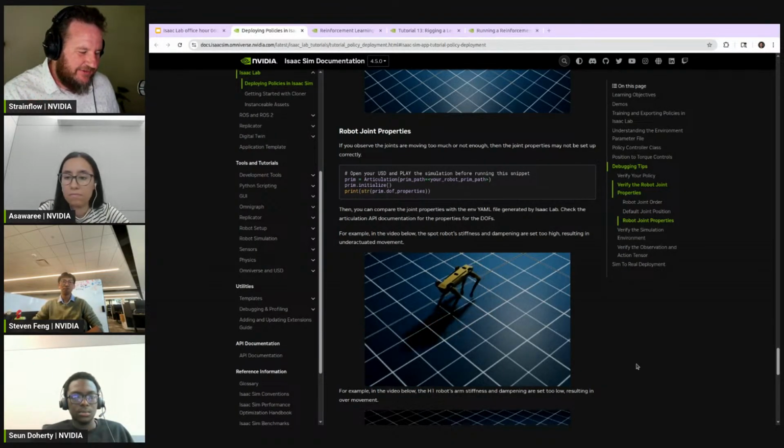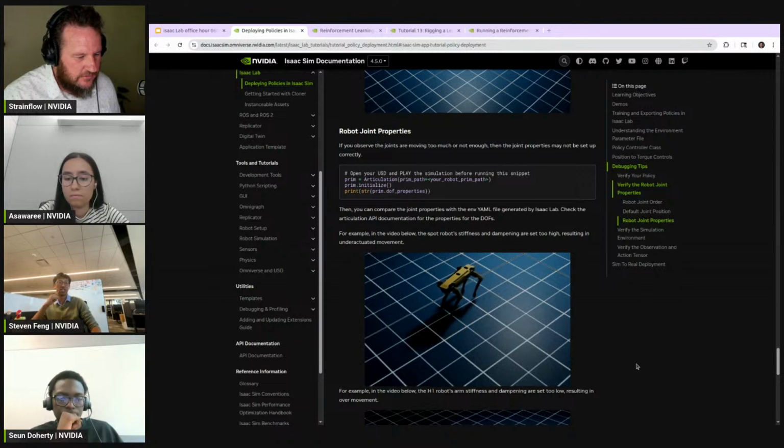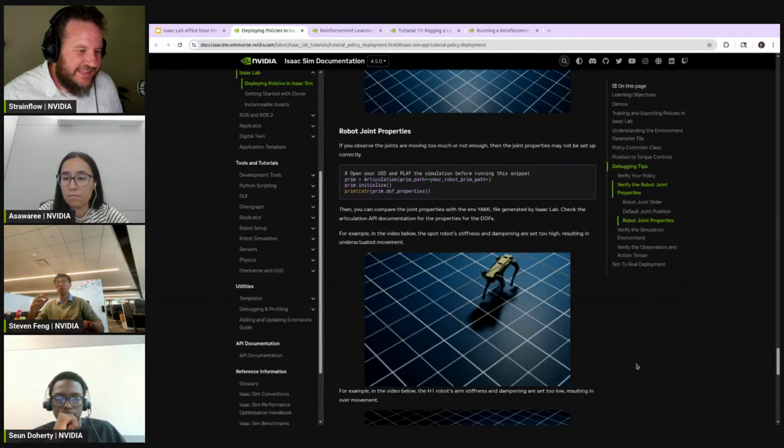Yeah. But a stiffness is actually, if you move a joint and take off the electrical signal, it would return to its initial position. Initial position, yeah. In this case, when we were moving it, you can almost think of it as your target position is where that neutral position for its stiffness is, and then it's trying to pull the robot towards the target position you're setting it to. If your stiffness is too low, it won't quite. Oh, right, with the stiffness.